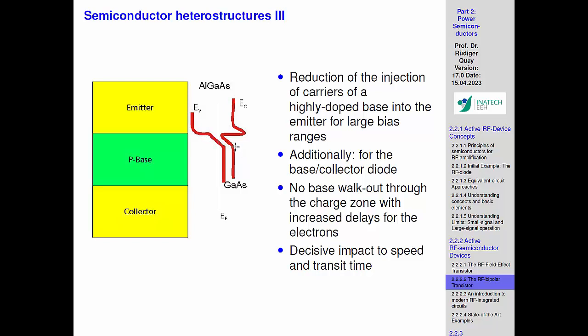And in the valence band, it's always a bit strange because you have to think differently. So here in the conduction band, this is a barrier, yeah? And for holes, going down in the energy band is a barrier. And by putting this emitter into a second barrier, so we take a larger band gap device here. So we're not taking gallium arsenide as we did originally, but we're taking something with a wider band gap. We build another barrier here for the holes.